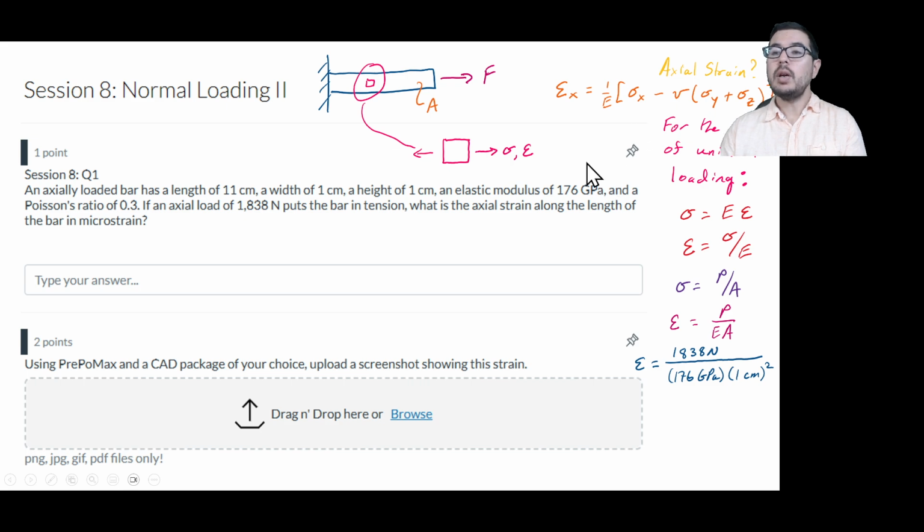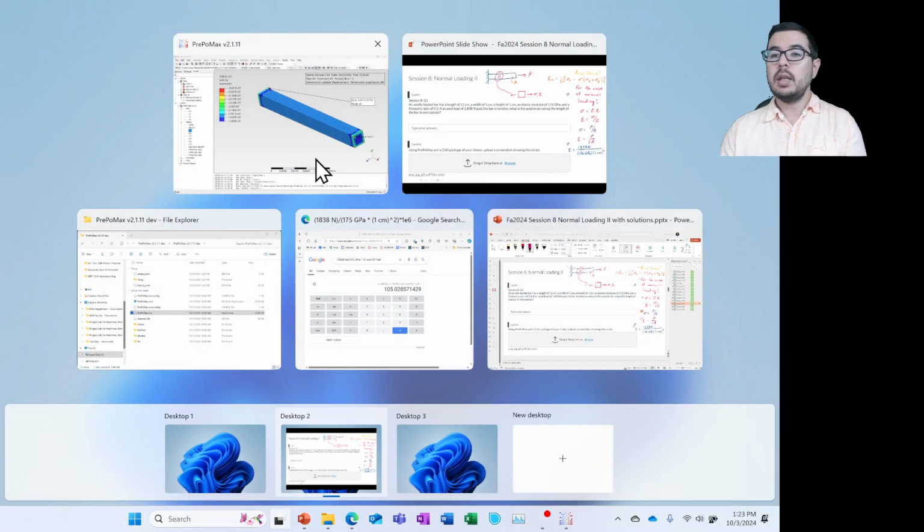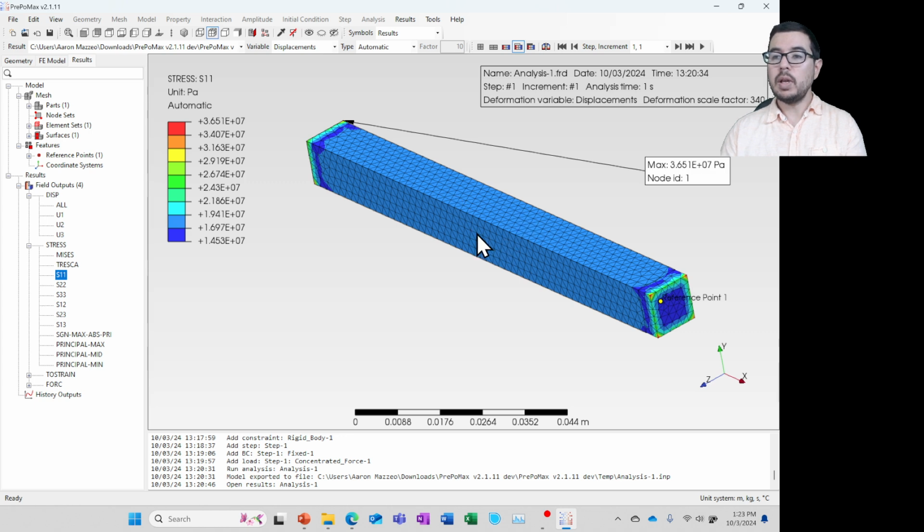So here, the material model predicts that you're going to have some strain in the orthogonal directions, but these walls are saying, no, no, no, you cannot move. You cannot do that. So when that happens, the material actually doesn't move here, but we have some stress being induced along these edges. So what are we going to do? Are we frustrated? This is not 18 megapascals or 18.4 megapascals.